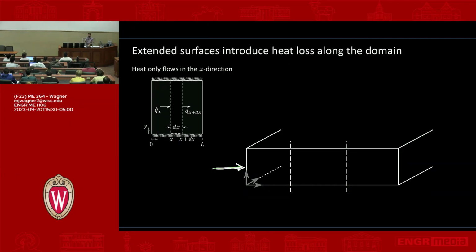If we're doing that, and we looked at the temperature profile at these different positions that I've drawn here, what would we see? Well, as you go further down the fin, you're losing heat, right? So the temperature is going to be dropping a little bit. But you also know that there's heat going out the top and heat going out the bottom. So if you sketch the temperature profile, it might look something like this.